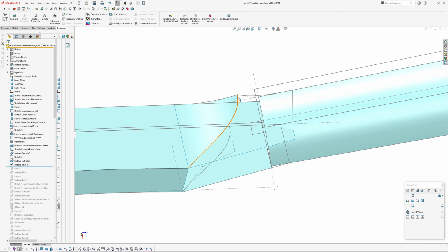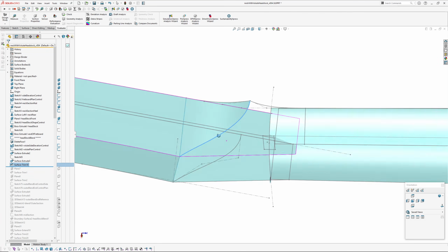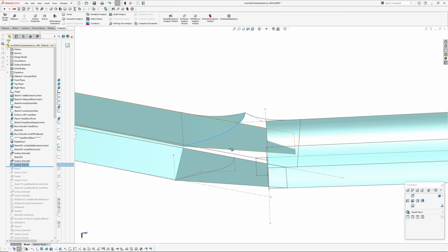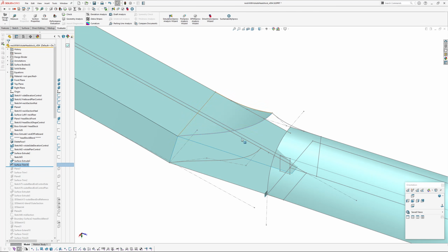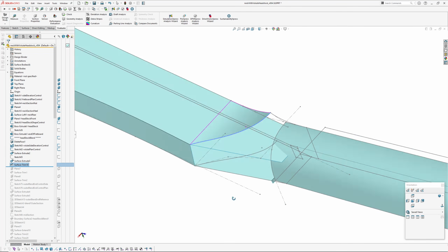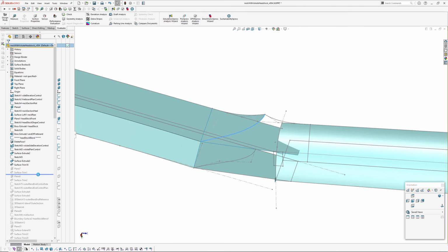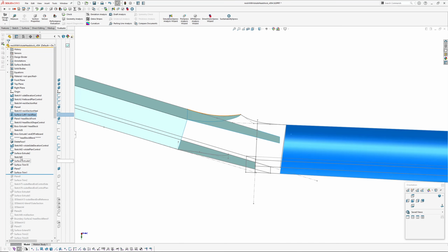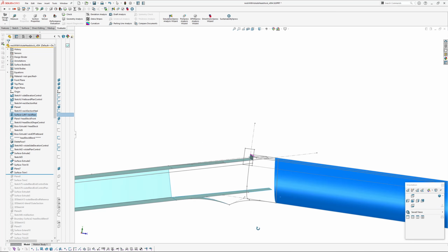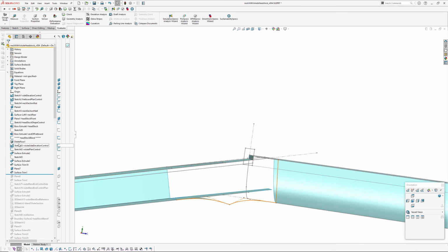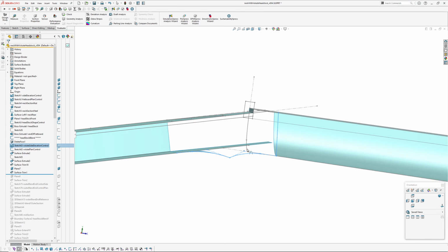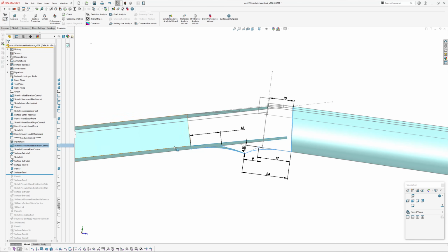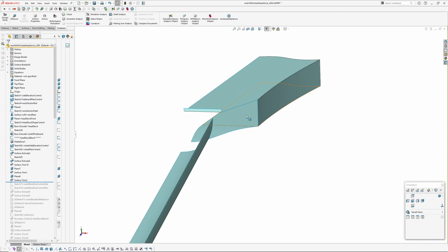Okay, so this curve here is explicitly modeled. It's not an intersection of overbuilt surfaces, so I'm modeling exactly up to that edge. That is the volute, if that makes sense. Next, I've trimmed back the neck here. And again, that distance of trim is in the volute side elevation control, as you can see. So a good dimension at the top there as well for that trim.